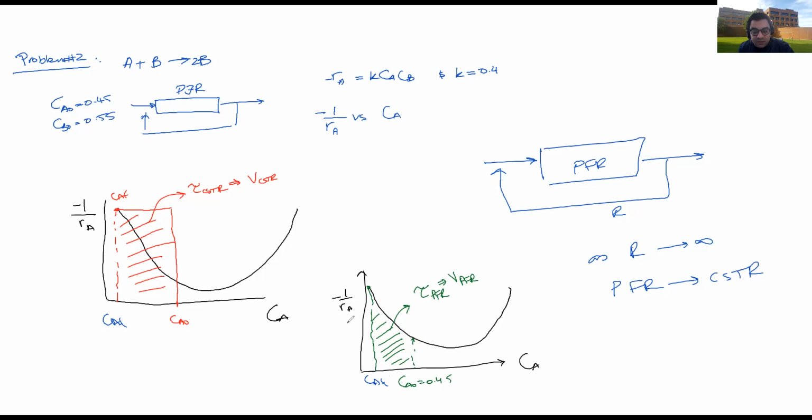So since this is the case, a PFR is recommended, and there should not be any recycle. No recycle, so the recommendation given by the simulation is not valid. It's just simple, so you always take it back to the basics.